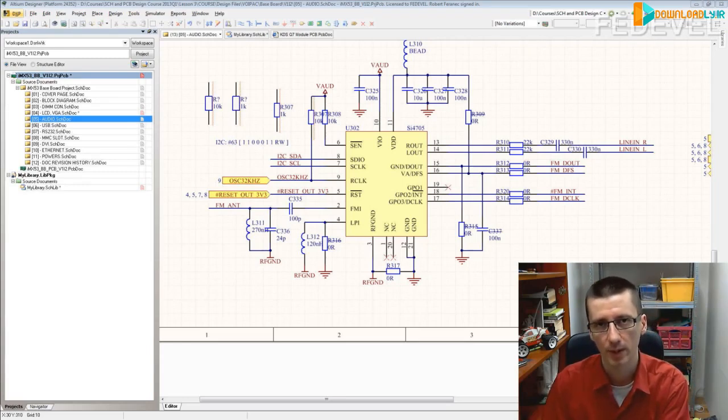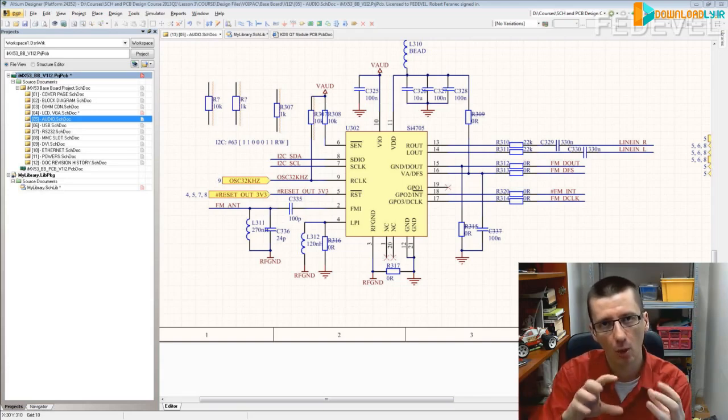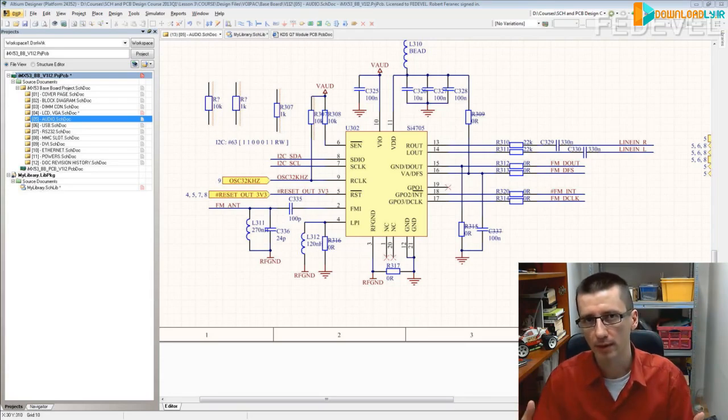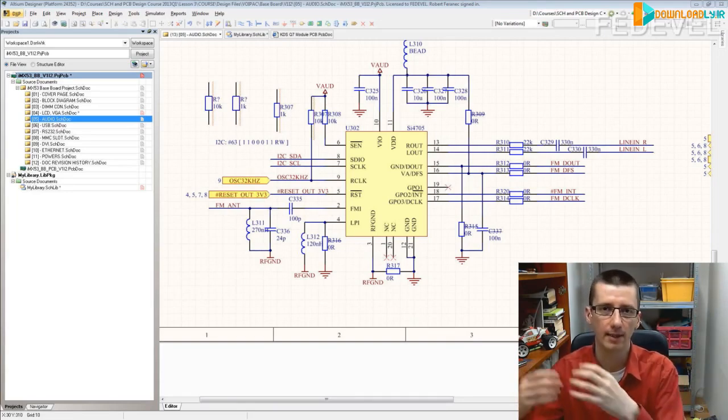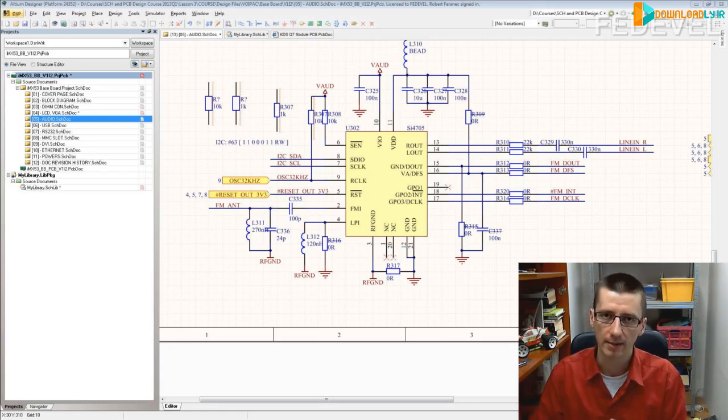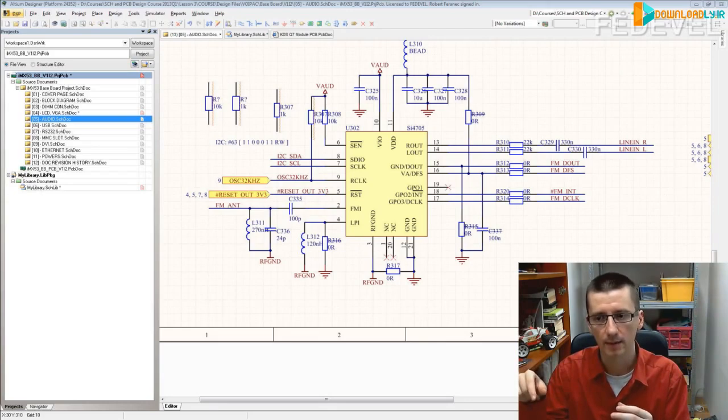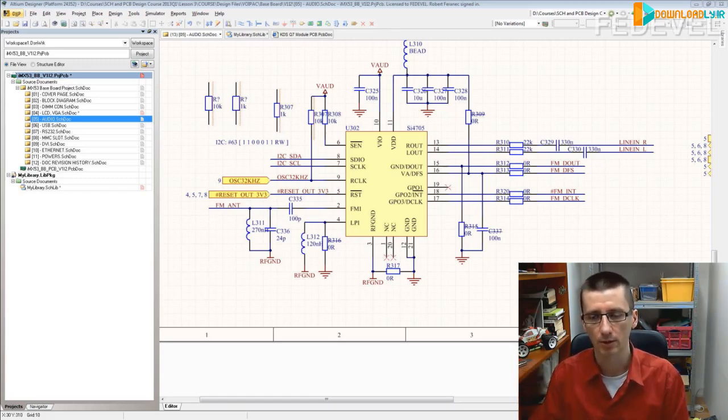In the second lesson we were speaking about how to put the reference schematics into your own schematic, and then basically in the next step you need to connect the reference schematics together, because you may have a reference schematic from a power supply, from a CPU, from something else, and they need to use the same net names, same signals. That's when you will make the connection.